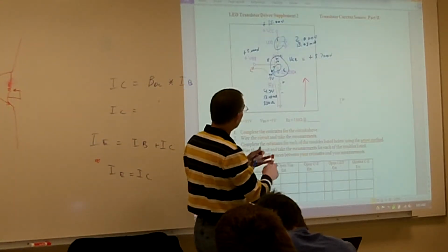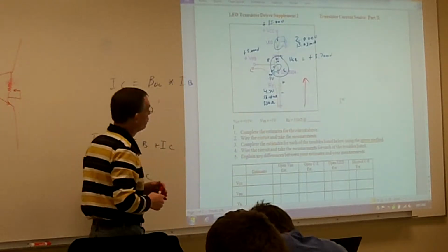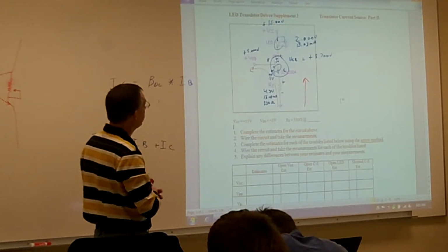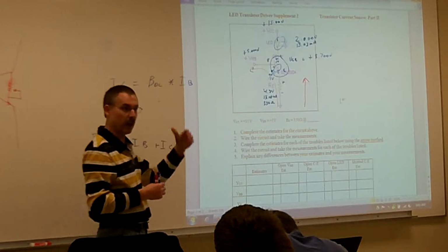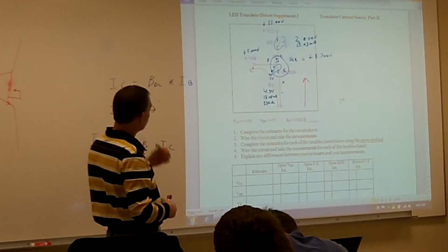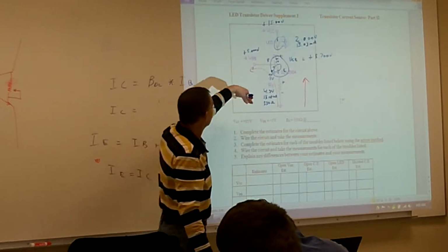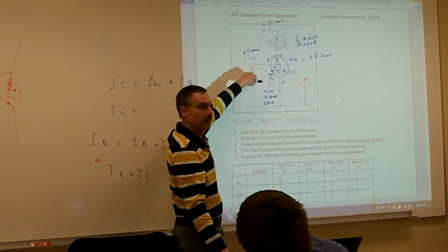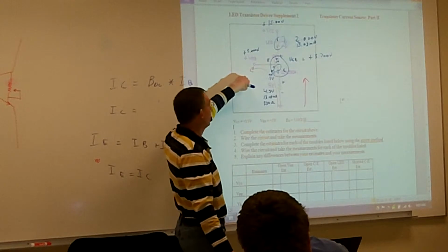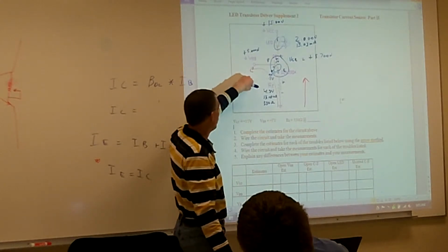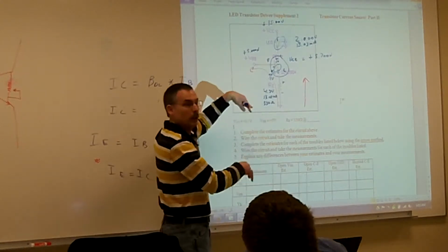That took its 0.7 volts. I got the voltage going across my resistor. I got the current going through there, and it has to go somewhere. So now it's going to go back to the base. Then what's going to happen is that the impedance of this thing drops. Now I got 13.03 milliamps of current going on my base. That means I'm really loading this circuit down.